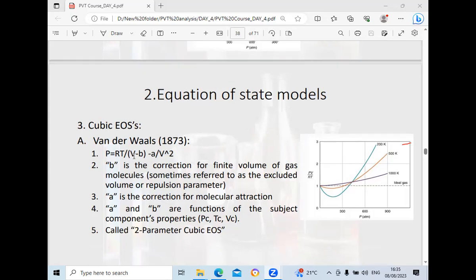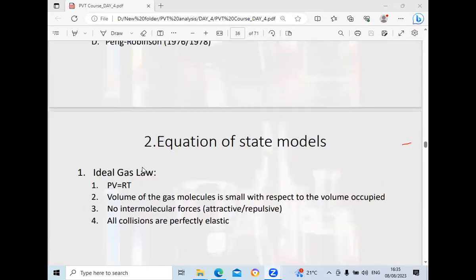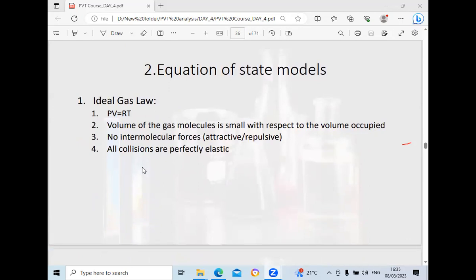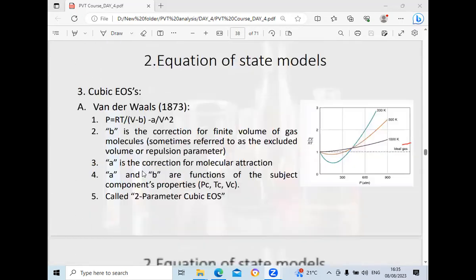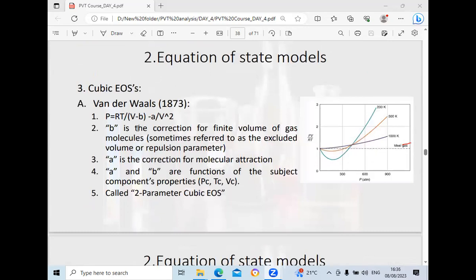And that is the reason why we don't even need an equation of state for black oil modeling. Why? Because the volume does not really change that much with PT condition. Remember, when we are talking of compressing gas, you can take air, for example, that can fill a whole room, and compress it to fill a very small container. But there is absolutely no way you can do that when it comes to oil.